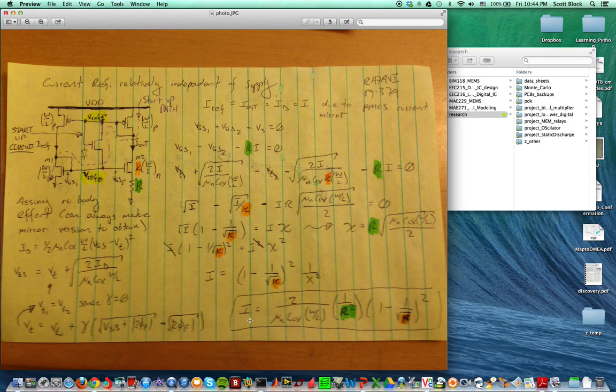And for example, like an I of 10 microamps in the 180 nanometer technology process that we're using, with a W over L of 5, I picked a 10 kilo ohm resistor and a K of 10. So I have 10 here, 1 there, multiples wise. But these guys have a ratio of 5 to 1. Okay, so I'm gonna show you guys a little simulation.